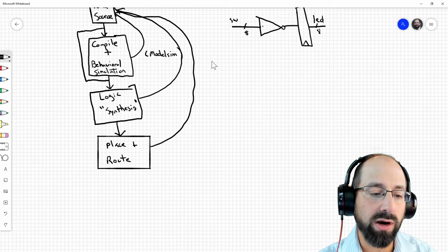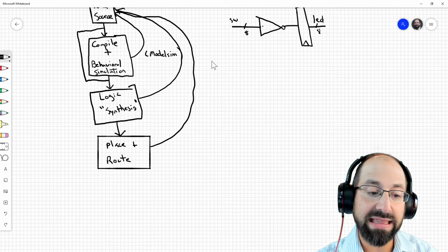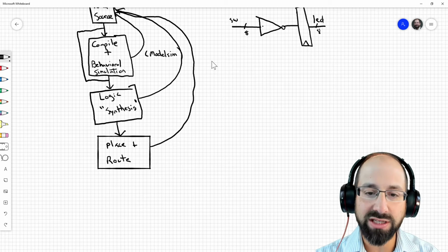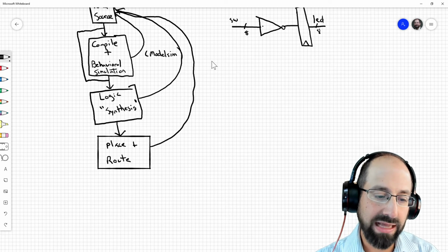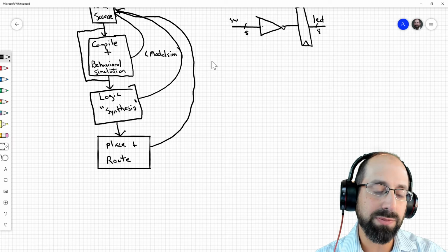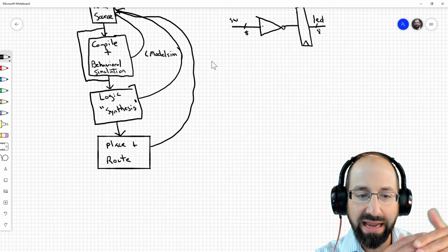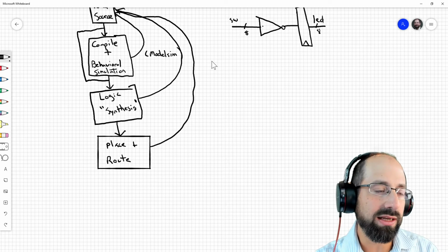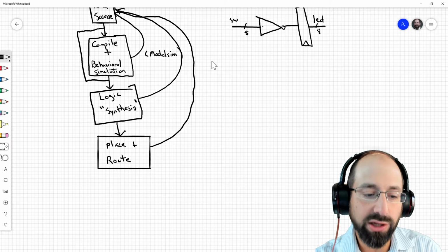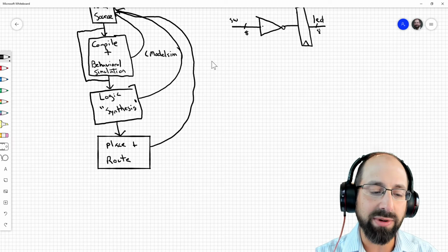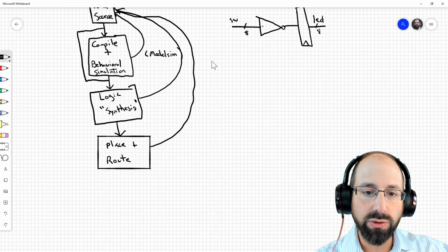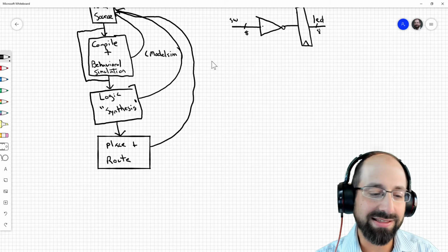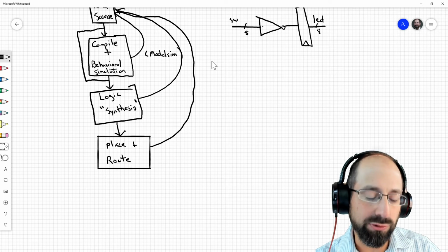But here is certainly also where it's going to take those elements that we got at the output of synthesis and put them physically somewhere on the chip, or at least build a model in which they are placed somewhere physically on the chip. That's why it's also referred to as physical design. That's the placement stage. I have those 8 lookup tables for my 8 bits of inverter here, as well as my 8 flip flops. They now actually need to physically go somewhere on the chip. In a 3-dimensional space, they need to go somewhere. It usually gives you a 2-dimensional view of what's happening. But in this grid of logic that's available to us, put stuff somewhere. That's placement. And routing is, I have all these things, I need to wire them together. How do I route those wires on the chip?